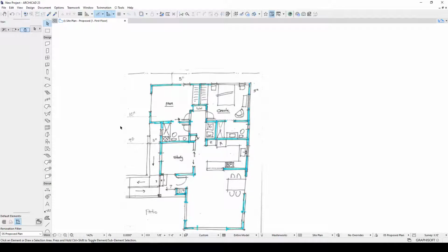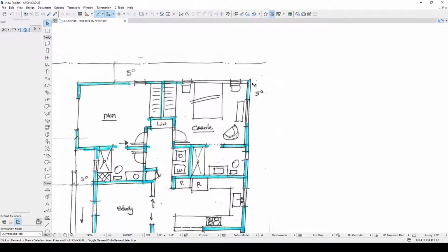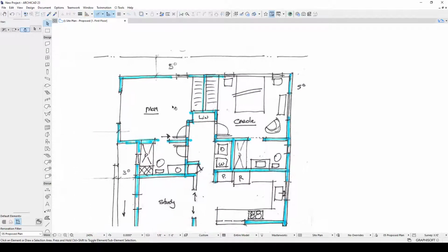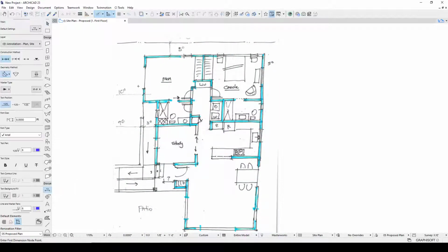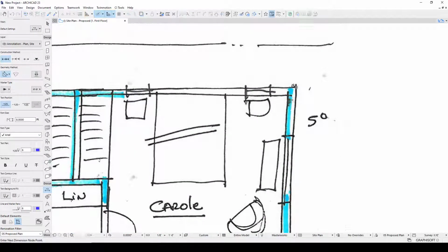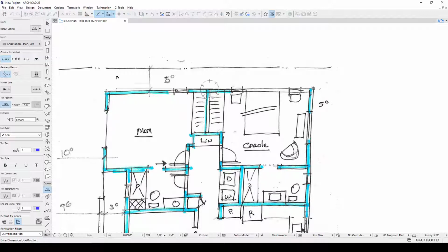So you have two choices now, and I use both. I can either use the line work here in ArchiCAD to create some rough lines to work with, or what I do is sometimes I print it and I measure everything, assuming it was printed to scale. In this case, since we have the computer here, I'll take care of it here. And I just want to get some rough dimensions. Once I start laying in the walls, I don't want to have to think too much. So I can come in here and I can actually do some measuring, but obviously they're not very accurate.